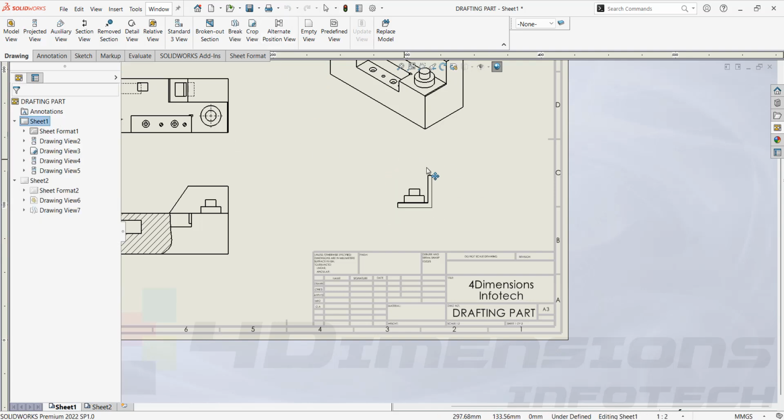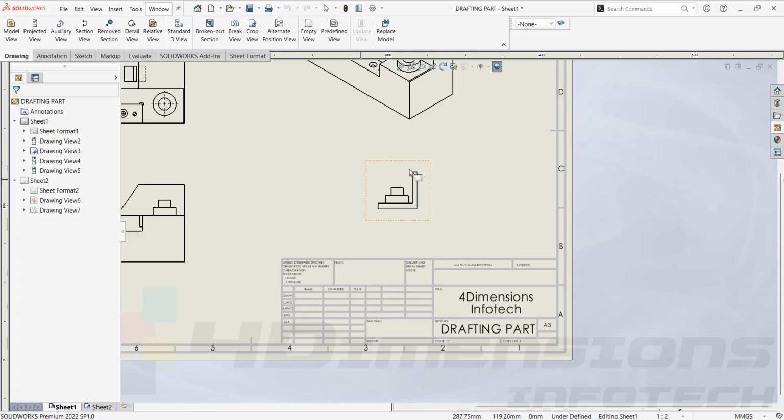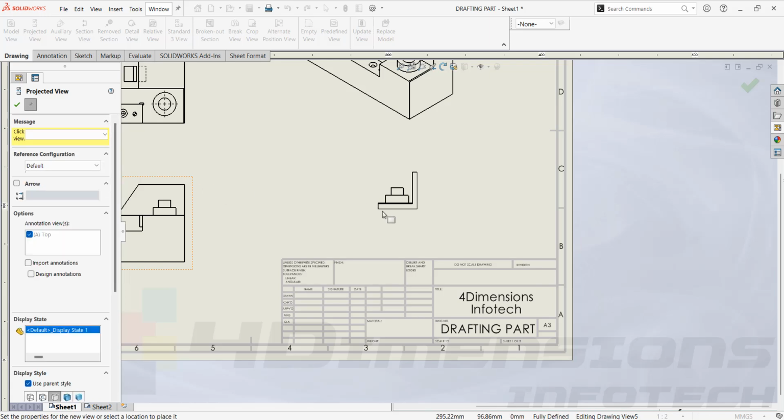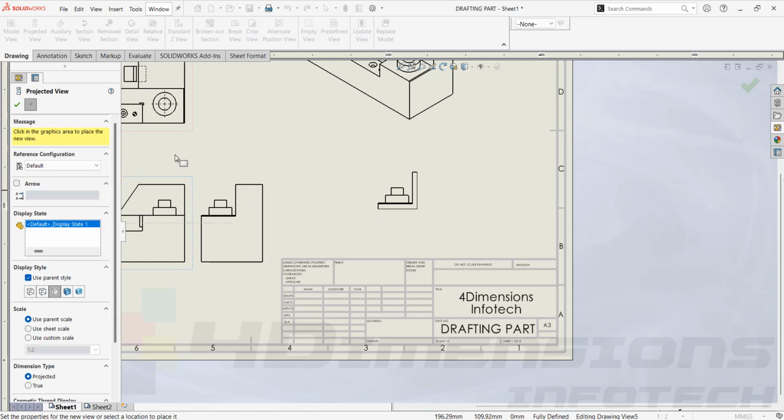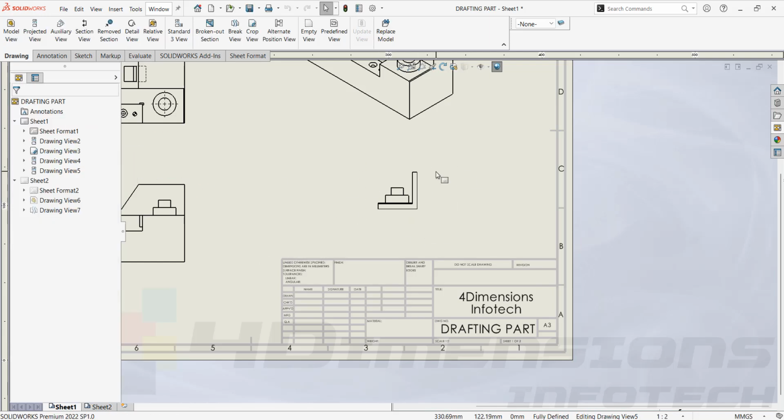And that particular view which was coming in the rectangular drawing has been cropped here. Other than that, everything is removed here. And this crop view is not reversible, meaning we cannot undo this crop view. If you want to show that view again, you have to project that view by this projection option and show it here again. But you cannot undo this option.